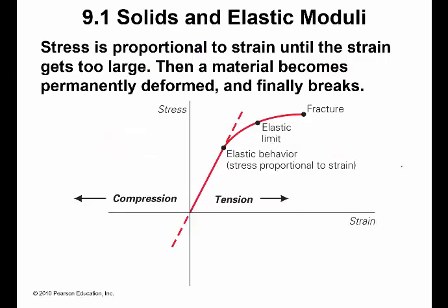So it's a natural way of thinking about it, although strain is usually presented just like this. When we combine our stress and strain, we can have a curve. And when I worked in industry, we did something very much like this, where we tested different solid materials that we manufactured, where we literally put them in a machine that stretched it until it broke. And so that's what we were interested in, so we could figure out the elastic behavior of that material. So we can physically think about this pulling, and our stress and our strain.